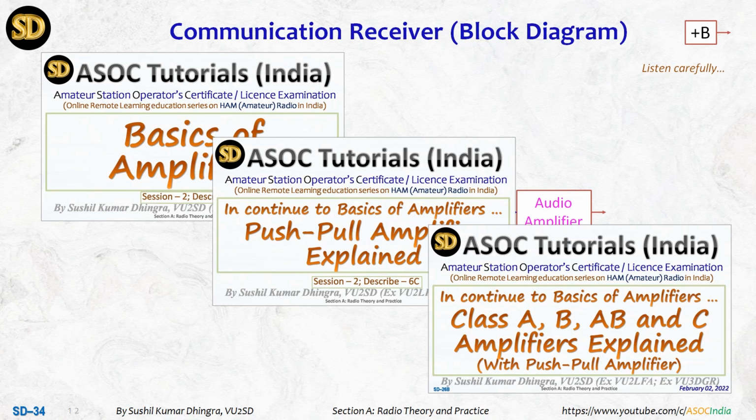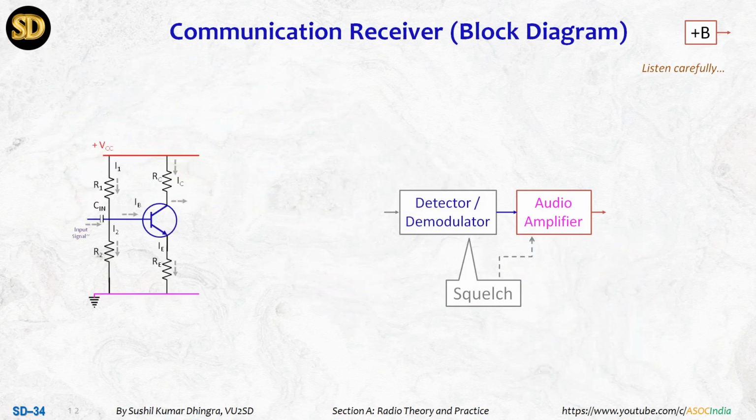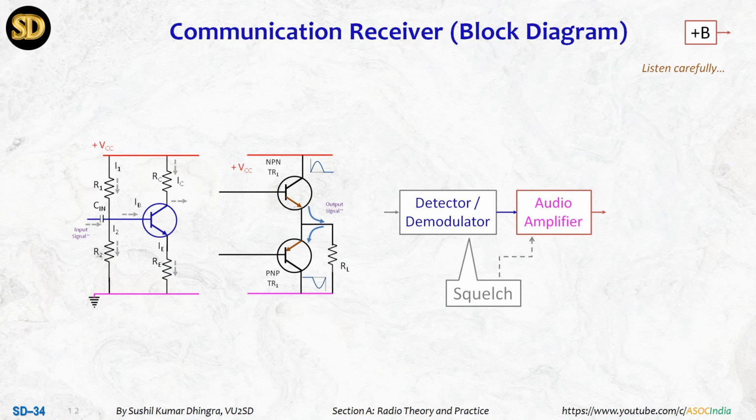So coming back to the amplifier, first remember there is a need for pre-amplifier stages to increase the voltage. This kind of amplifier is mostly used in the pre-stages, and this audio amplifier is a pre-stage. Once we have improved these pre-amplifier stages, we need a power amplifier, maybe class B, AB or C. So this one is a class B amplifier.